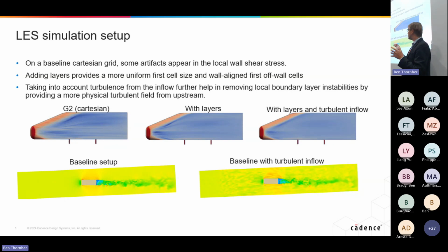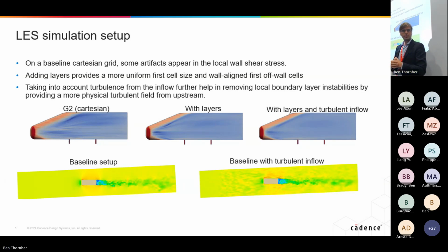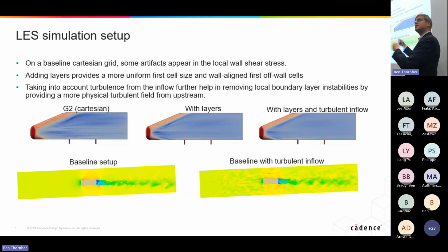You'll still see a turbulent pattern around the body, but that's all thanks to the inflow turbulence. And that removes, on average, these spurious lines that we can see. That is basically the solver trying to get to your turbulent boundary layer, but just informed by the fluctuation in the first cell height.